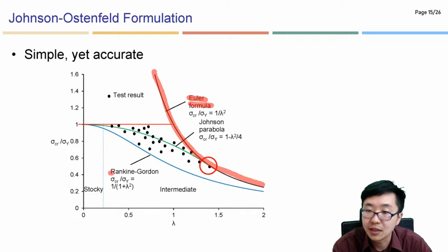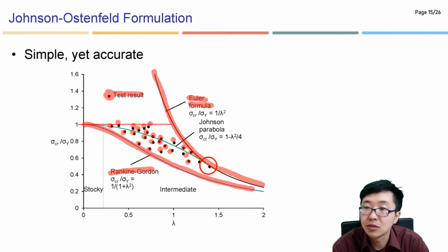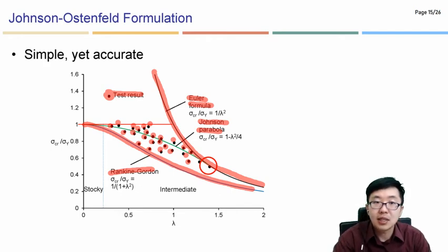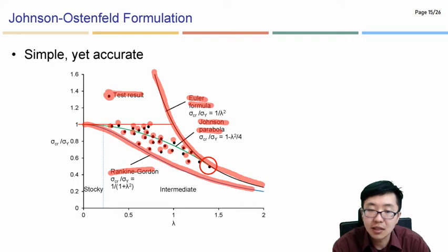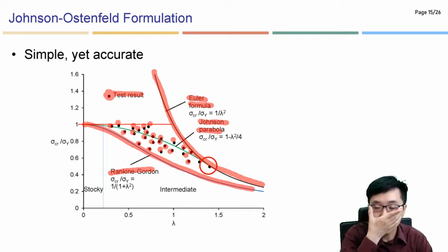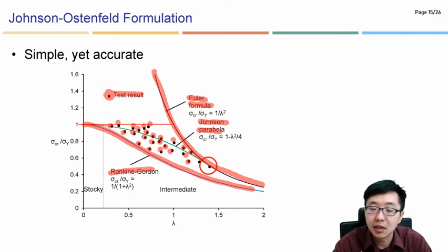And at the same time, we can see the Rankine-Gordon formulations, the blue line, and the dots here represent testing data from the experiment. Just now we learned about the Johnson-Ostenfeld formulations, shown here at the center, in between those two lines, Johnson parabola and Johnson-Ostenfeld. These might be considered more realistic formulations, but basically, as you can see here, that should be decided by we engineers' judgment.